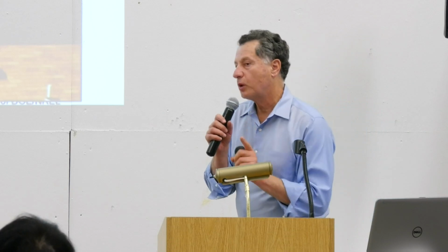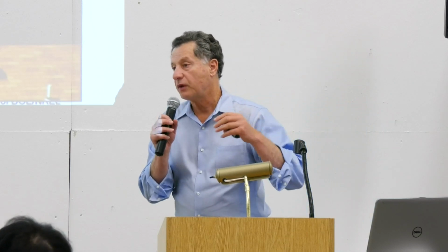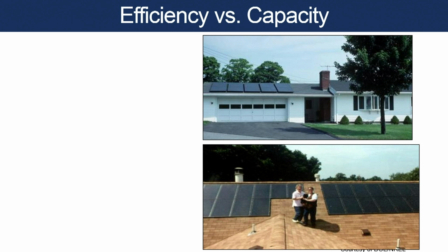Okay. So now I want to talk to you about one other term that's really important, and it really relates to what Bill said about the larger the building, the harder it is to get PV to cover it. The idea of efficiency versus capacity with solar. When you say efficiency in the normal work world, it sounds like a better term. If one worker is more efficient than the other, then you want to hire that person because they get more work done for the same amount of pay. Efficiency in solar means power per square foot.